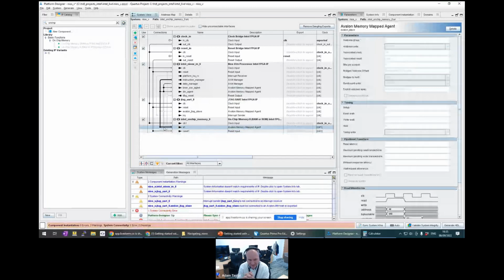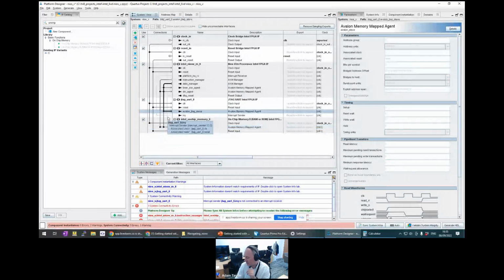So the processor can access the memory to get both instructions and data, and that's important. When we want to send data over the Avalon JTAG UART to transmit and to tell us what's going on, we click on this. We're just going to connect the data manager to it. There's no need for us to connect the instruction bus. So we can see our system now. We've got a fairly straightforward and fairly simple system.